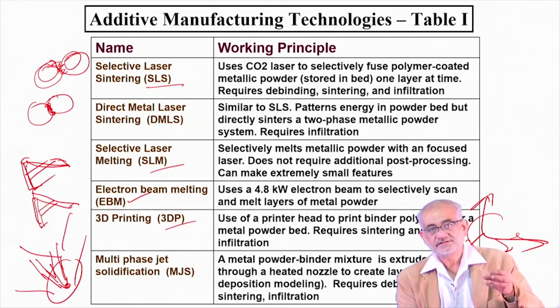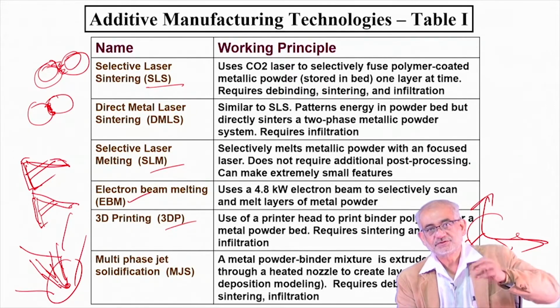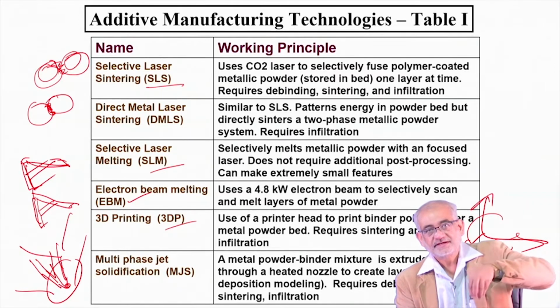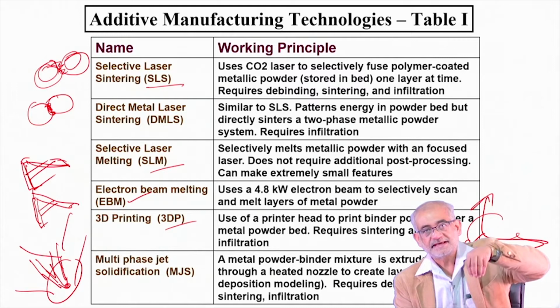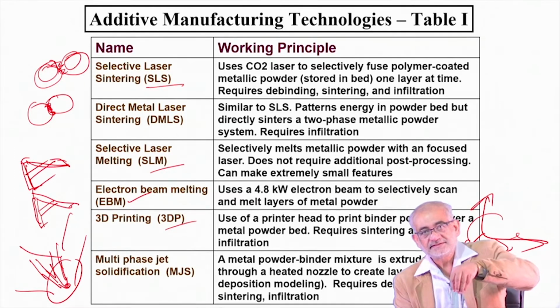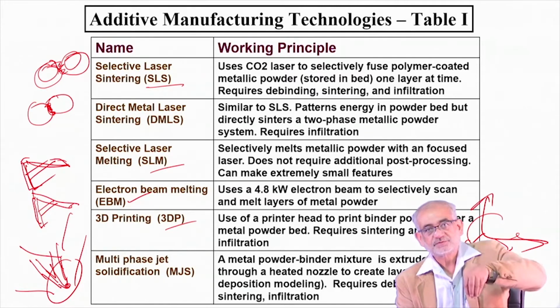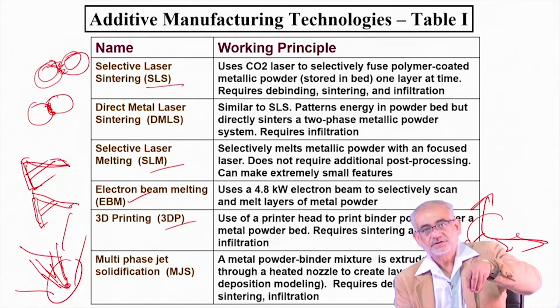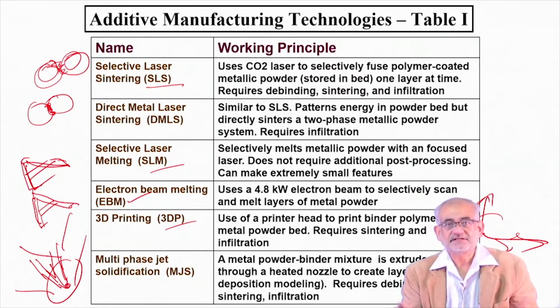This robot arm will carry the laser beam, the powder feeding system, and the concentric nozzle, and both will act simultaneously. If it goes through a circular, vertical, or lateral motion in X and Y direction, it can create practically any shape.